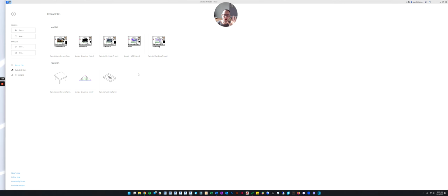So we've talked about previously the Revit file types, or we should have, but just as a reminder, there are three Revit file types. There's a template file, a project file, and a Revit family file. So in order to start a new project, we're going to start with a template file. So Revit, when you installed it, it came with a template file already. So we're going to use the default template file to do all of our projects.